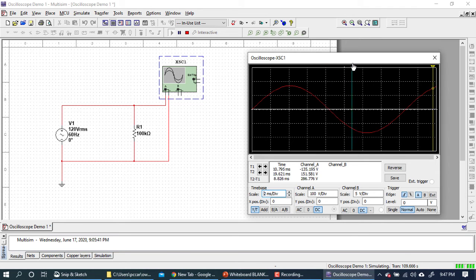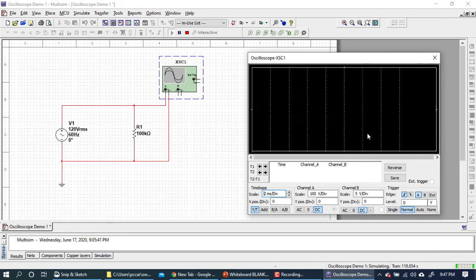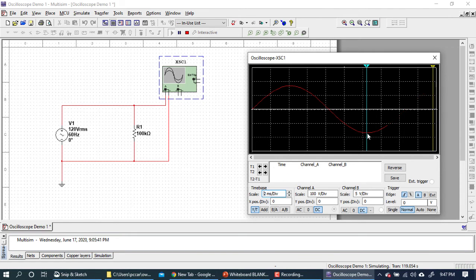What about 270 degrees? What do you think the sine of 270 is? Put 270 in your calculator and hit the sine key. I guarantee you it's -1. Look at that, -1 times the maximum voltage. Maximum voltage is 169, so that would be -169.